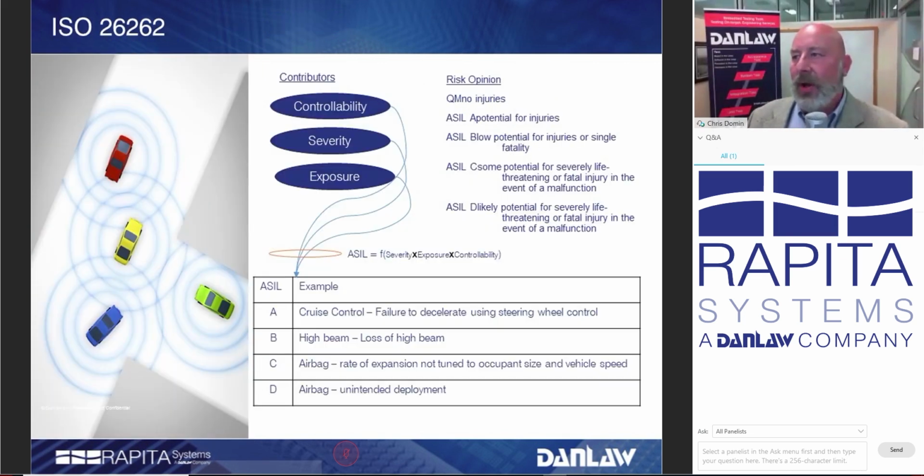Why is that? So in ISO 26262, there are additional requirements on a multi-core system. For those of you that are familiar with ASILs, or automotive safety integrity levels, they're used to calculate the risk of a hardware-software component, the combination of the two in terms of severity, or the type and extent of injuries to the driver and passengers, the exposure, that is how often the vehicle is exposed to the hazard, and controllability, which is how much the driver can do something to prevent the injury.